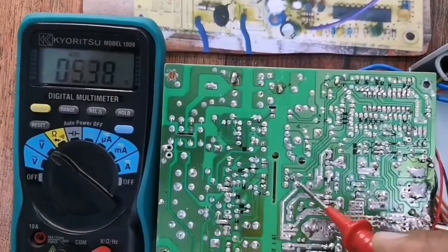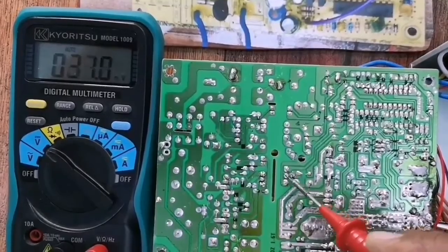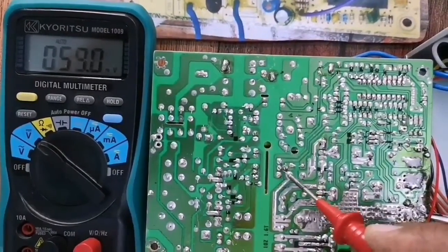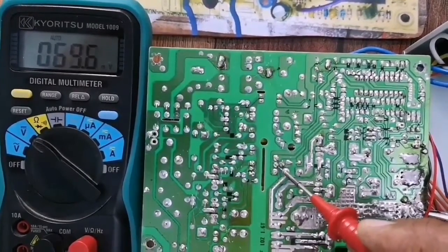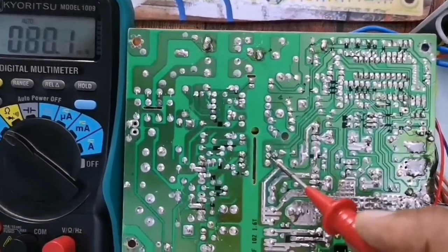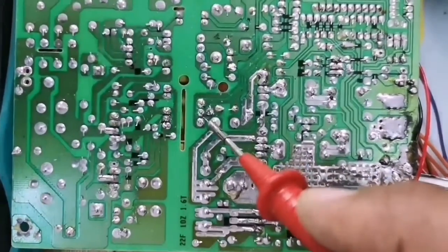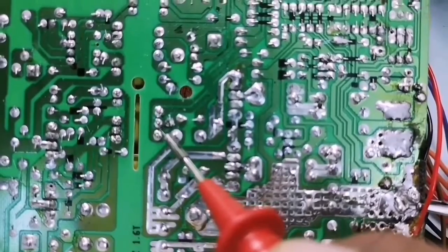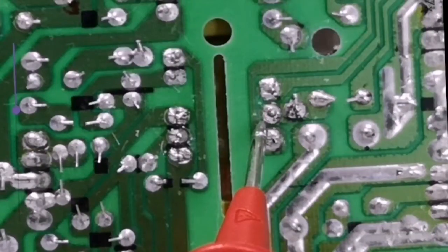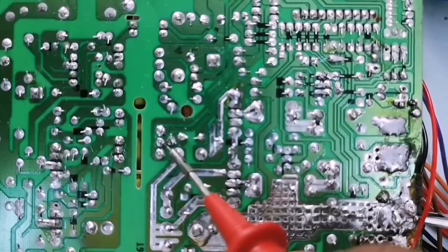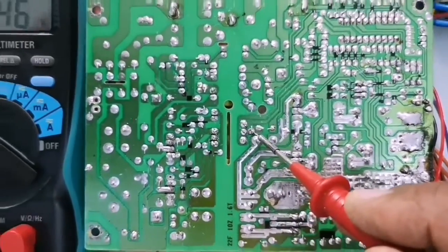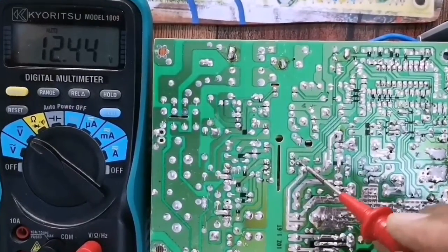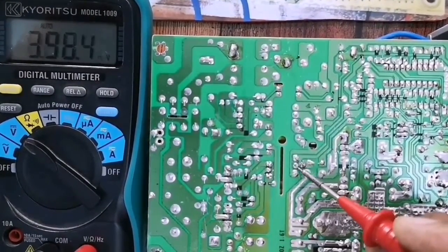And I have noticed a very important finding here. It must be the cause of the problem. If you can notice, we really have a dry or cold solder at the middle pin, so it is not connected. See, the voltage is reaching the PCB track but not appearing on the pin.